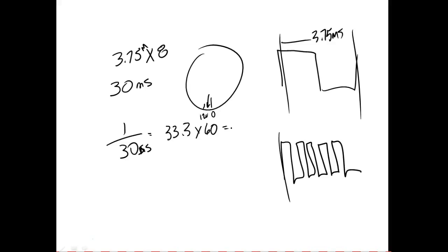So normally your encoders are going to have multiple blades on them, and it depends on the resolution. How good do we want to make this? If I was going to use this for positioning the motor, then the closer the blades are, the better I can position it, right? So we can use incremental encoders for several different things. If we use multiple LEDs, we can determine direction.